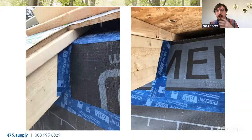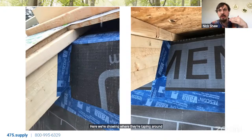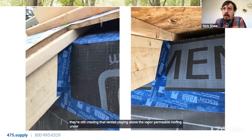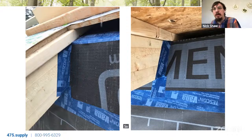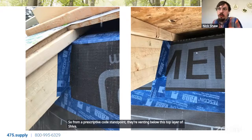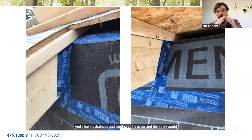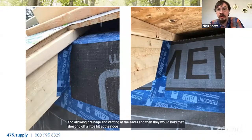Here we're showing where they're taping around that continuous rafter, but they're still creating that vented plane above the vapor permeable roofing underlayment. So here you can see they're still allowing drainage and venting in this location. This is above a structural sheathing, but they have an additional layer of sheathing to hold their roof finish. So from a prescriptive code standpoint, they are venting below this top layer of sheathing and allowing drainage and venting at the eaves. And then they would hold that sheathing off a little bit at the ridge to allow venting at the ridge cap there.